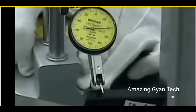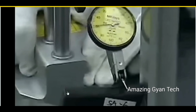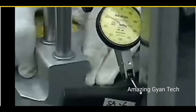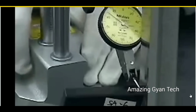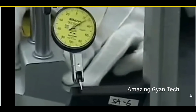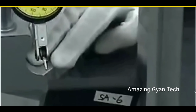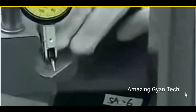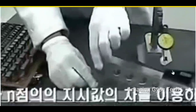So in this case what they are trying to do is make this one parallel to the surface plate. This is the surface which they are going to measure. This is the control surface. So this is a detailed video. You can see how the operator uses the sine bar and how he sets it out.